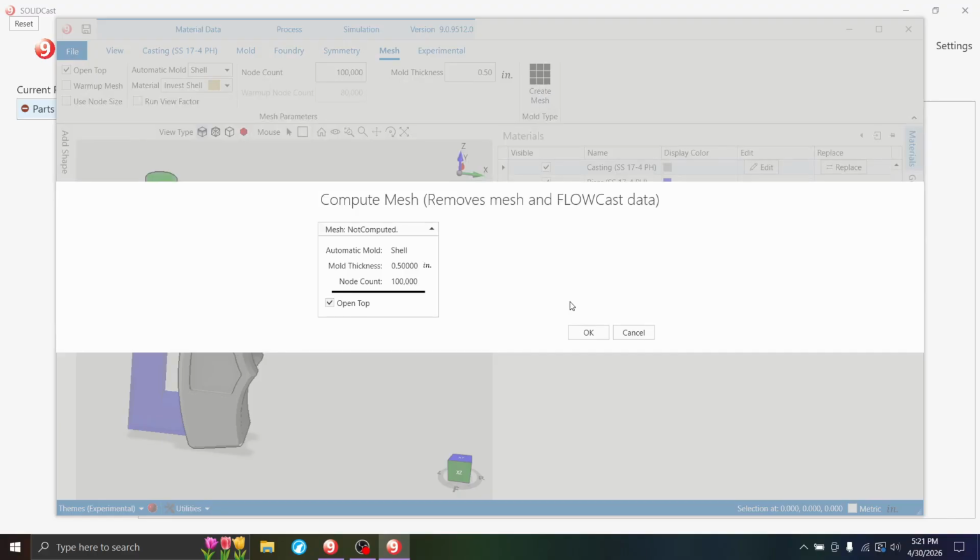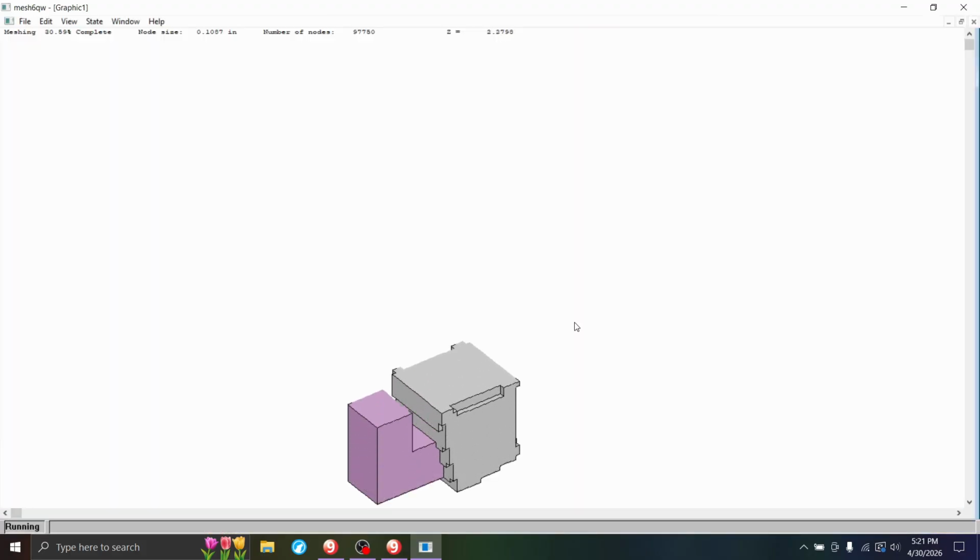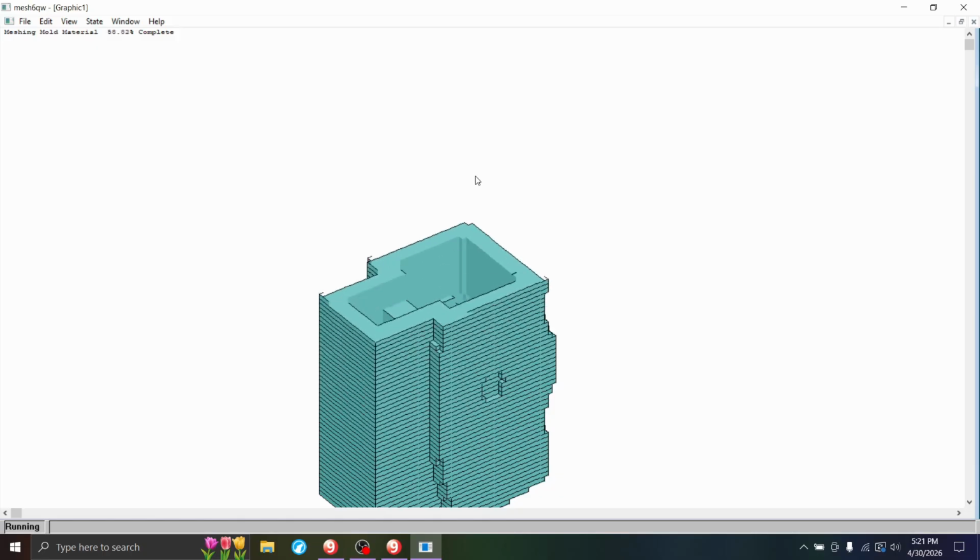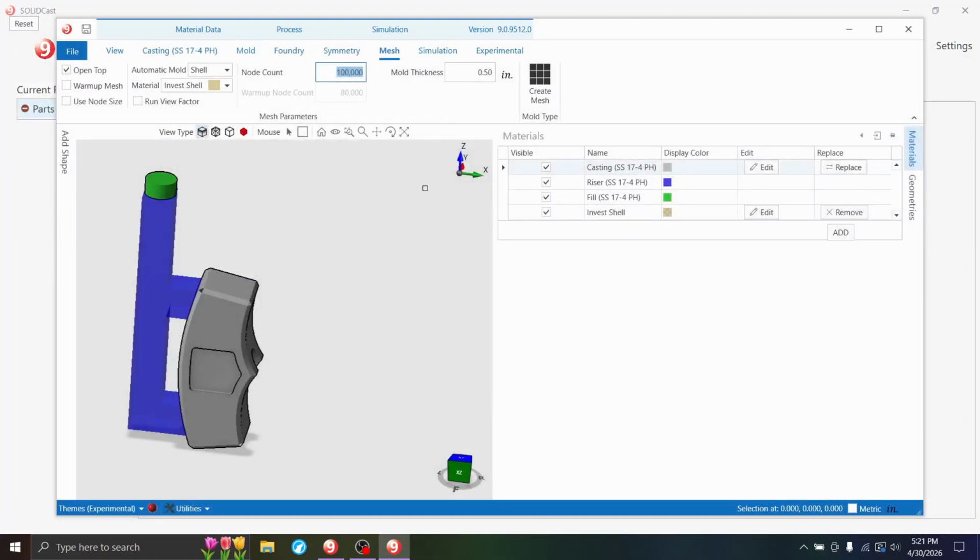And click OK. And every time you edit any of the mesh properties, you're going to want to rebuild your mesh from scratch. And that's what will cause your updates to take effect. So there we just saw it calculate the areas and build the shell.